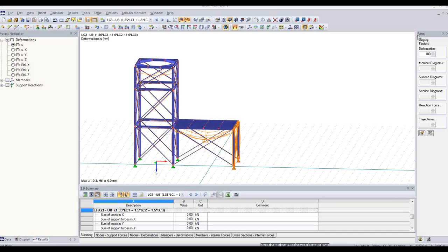The analysis can be done according to first order, second order, or large deflection analysis. So you are able to include P-delta effects in this analysis, and if you need to, you can also use objects like cables for cable stay towers or guide towers that you can analyze, and just as we have seen, model it as a regular member, and you will be following the cable theory for analysis of those members.